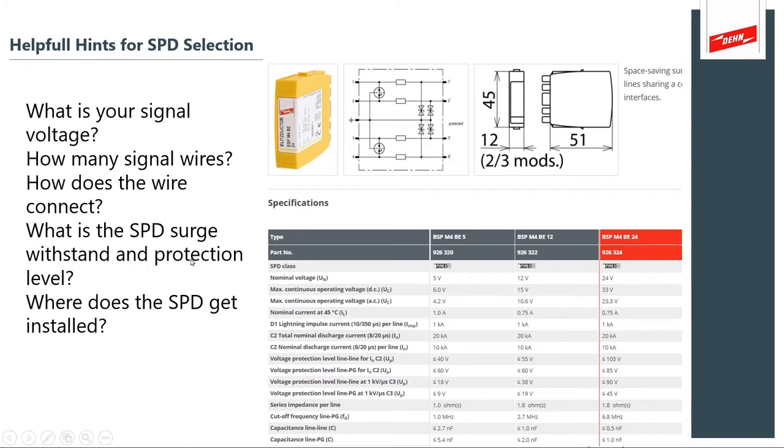What is the SPD surge withstand and protection level? This is important to understand if the SPD is rated to the surge rating of that type of exposed signal. And then where does that surge protector get installed? Is it on a DIN rail strut? Is it directly at the instrument? These are the questions that you want to ask yourself, so that when you're looking over your design and when you're evaluating the installation, you can tell if it is properly selected.